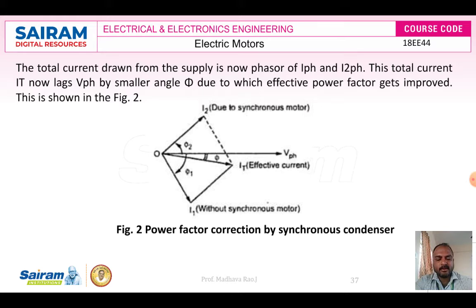Now, even though the current lags the voltage, the power factor is improved. The angle is decreased and the power factor will be increased. So, you can see with and without the synchronous motor how the power factor varies.